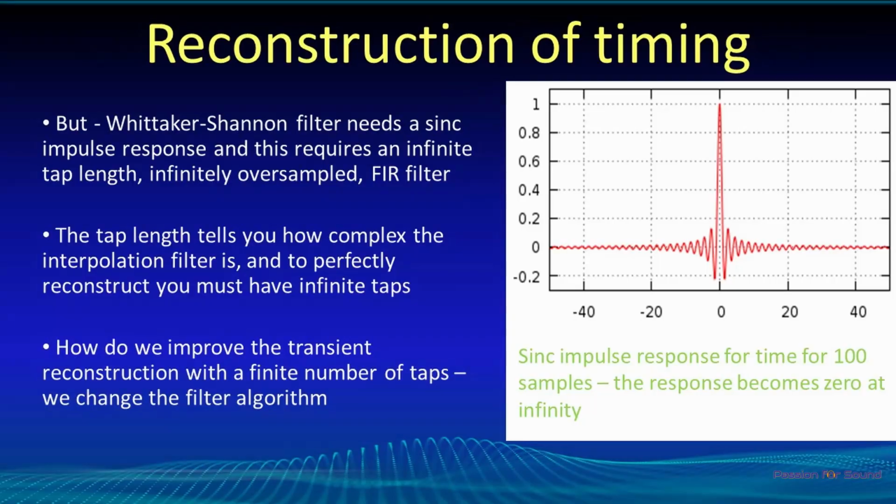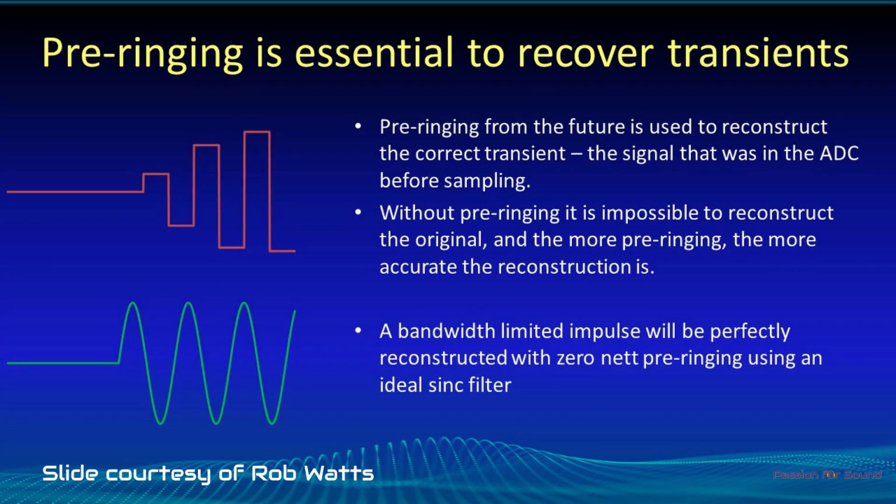And the reason they've got it completely wrong is that sampling theory requires that your signal to be bandwidth limited. So it can go up to 22.04 kilohertz, and at 22.05 kilohertz, it has to be zero. That's what you mean by bandwidth limiting. Yep. But when you use an impulse, your energy at 22.05 kilohertz is exactly the same as the energy at DC, because it's not bandwidth limited. And when you put a bandwidth limited impulse into a sinc function, it just does not ring at all. It will reconstruct the original signal completely perfectly. There'll be no extra ringing.